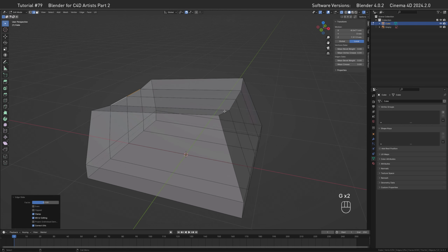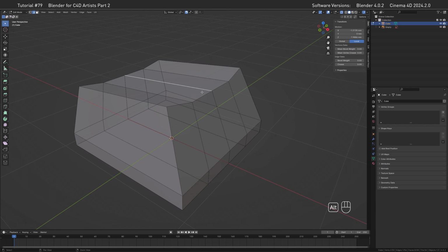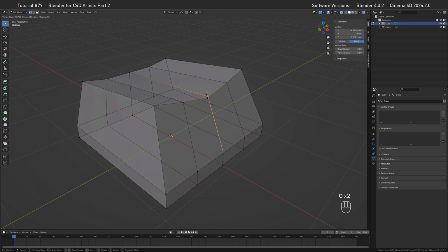So we keep it all at an angle. Let's also do that for our middle points by going to the keyboard, 1 to get into vertex mode, select those vertices here, and then disable snapping, and then G Y again. So what I want to do here is make this a little bit more shallow, so I'm typing 0.05 here. And do that for the backside again, G Y, move down 0.05.